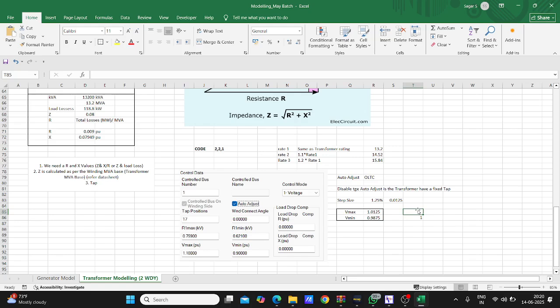You got it, right? If you want to adjust the tap, I need to either increase or decrease it to maintain the nominal voltage. So this means that if we change the tap position of the transformer, the voltage will change by 1.25% of the nominal voltage. Got it. That's good. Super. Thank you, sir. V maximum and V minimum you should give.